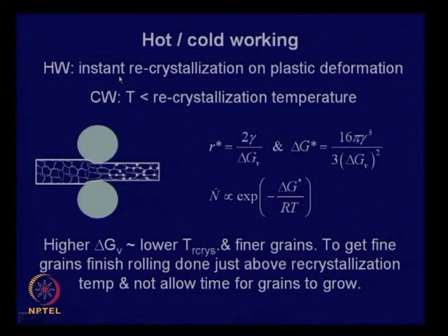So, it is not a fixed quantity, and if we understand the factors that determine the recrystallization temperature, we will be able to design a thermomechanical processing route by which you can get the best combination of strength and toughness.